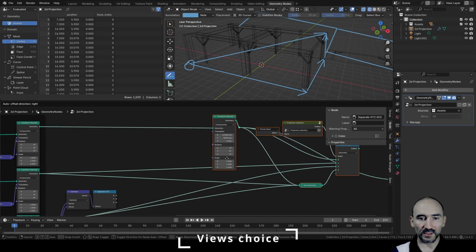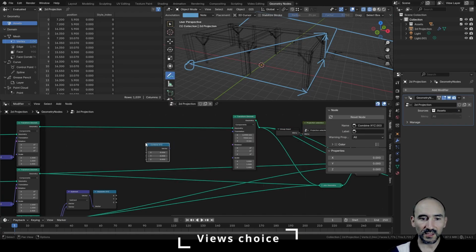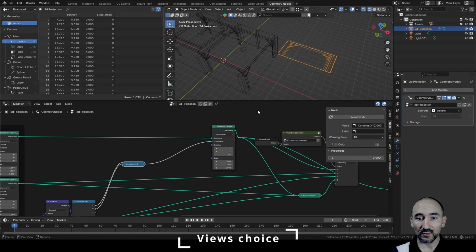I can move all these nodes a little bit. I can add a combine X, Y, Z, and what we need is to take the X, the Y, leaving 0 on the Z, and I can link these in the translation of this geometry, and the result is exactly what we want. So now the position of the 2D projection is correct.